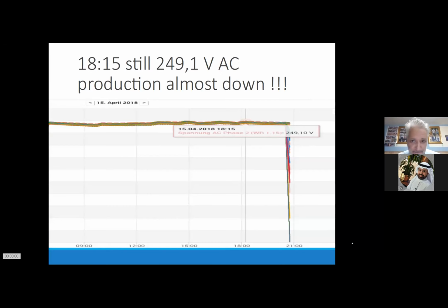That's, like I said, most of the inverters derating the output at 250 to 255. You will never know for sure how many percent they are, but they start getting hotter, and then they derate. The DC voltage goes up out of the perfect MPPT range and actually decreases the output.